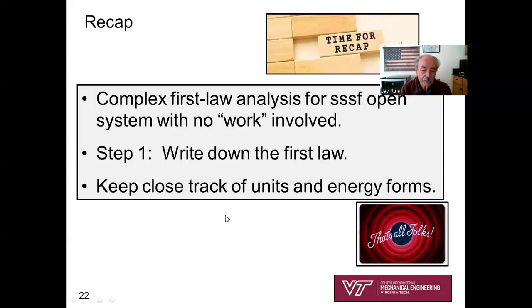Okay, so the takeaway of this full combustion analysis, where we determine numerically the heat released from a hydrocarbon and air combustion situation, is that it's a complex first law analysis, steady state, steady flow, open system. No work is involved. The first step is writing down the first law with those complexities we talked about.